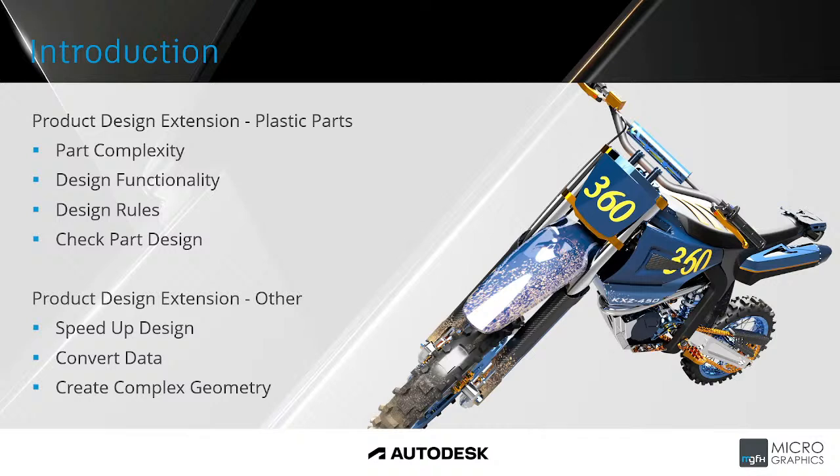We can also use the convert option to convert mesh data into T-spline data. So if you're doing reverse engineering, we would be able to convert data in that reverse engineering environment using the organic conversion option in the extension. And then lastly, you may want to be able to create complex geometry quickly, and we'll see with the tools available to us that that helps us create that geometry.